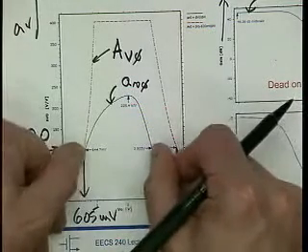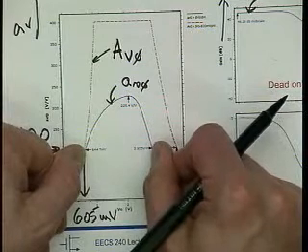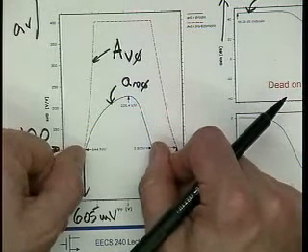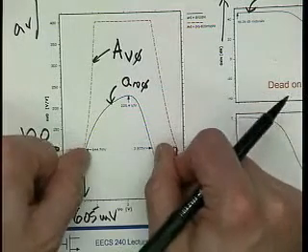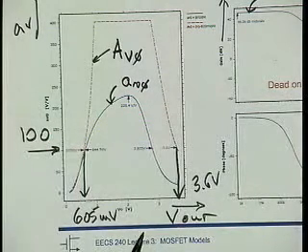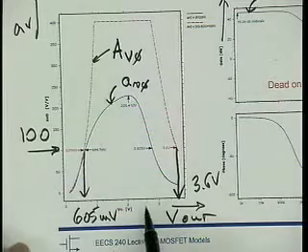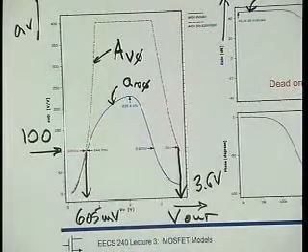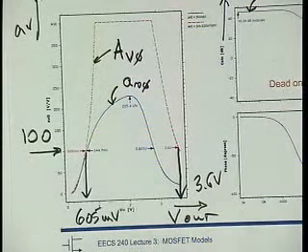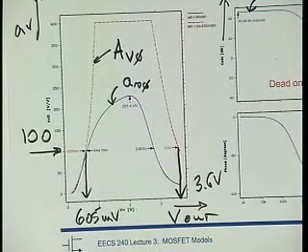Notice that the lowercase av0 actually would only go up to 2.8 volts, so that would be a problem, but again, most of the time we care about the red stuff, not the blue stuff in this graph. So in a way, of course, depending on how we build the current source, we can go from 600 millivolts to 3 volts or so with this amplifier and maintain a gain of 100.